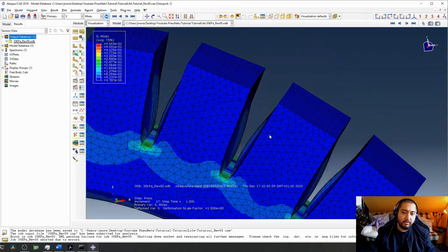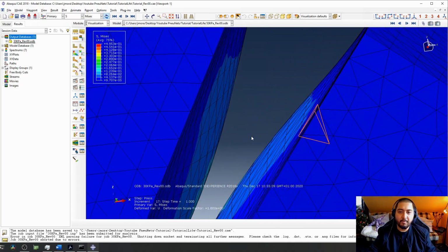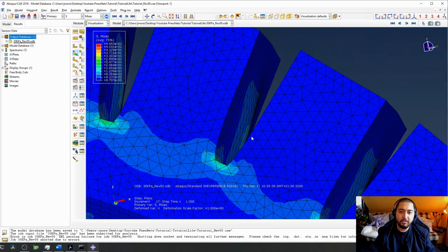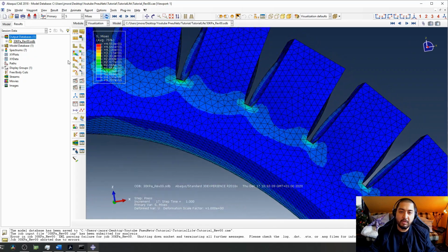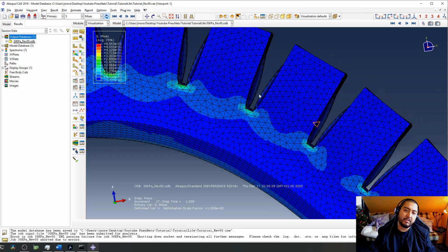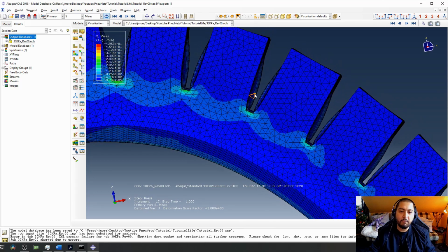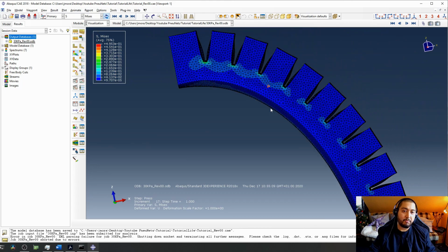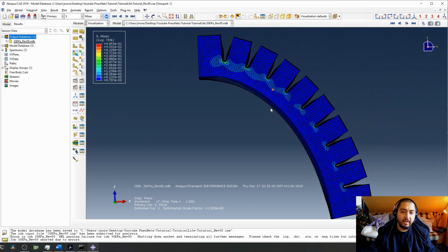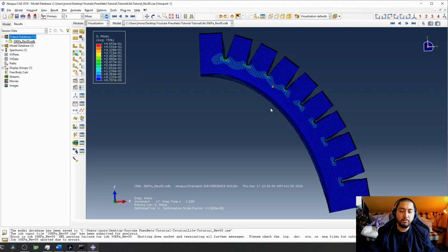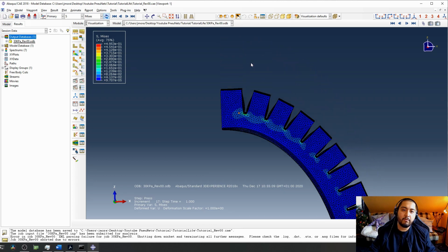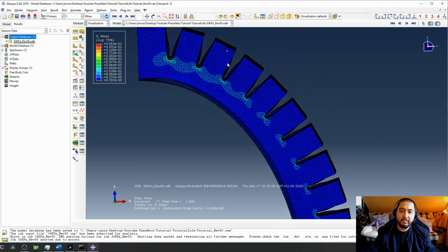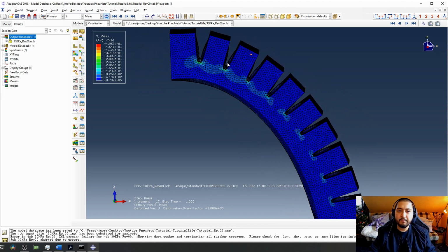As you can see, we defined the contact of these surfaces, but we didn't apply enough pressure. 30 kilopascals is not enough pressure to have them in contact. But if you create another job with maybe 40 kilopascals, maybe 45 kilopascals, you can have the contact, and it's going to expand higher, of course, and continue the bending motion. In some research you can find that the actuator bends all the way until here. Of course, everything depends on the parameters of your geometry.